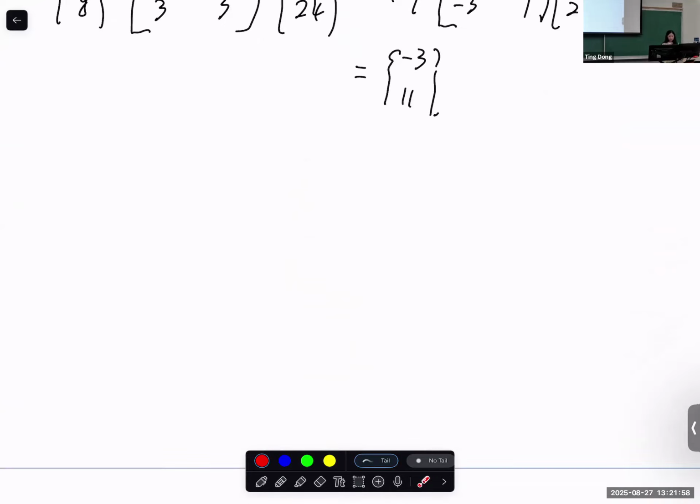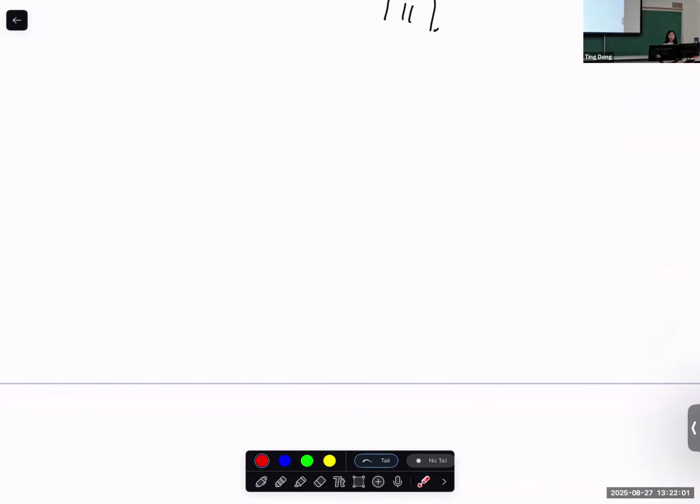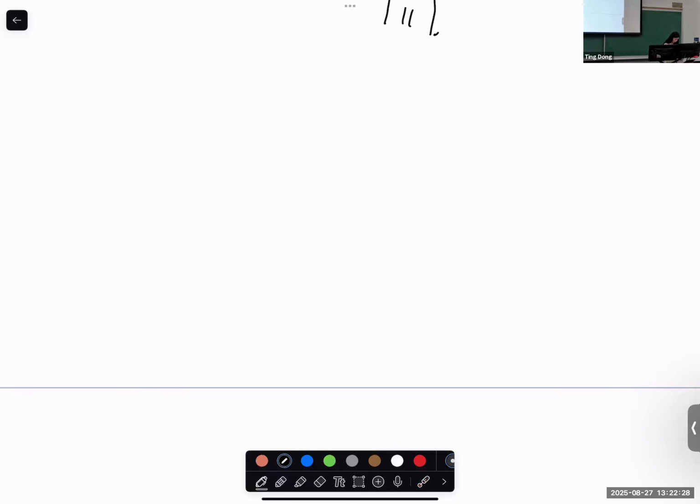We start with the simplest element type, which is a spring element. A spring element is simplest because it can only move in one direction, right? Let's say you have a spring, you cannot apply a force like this. You can only apply a force in the spring x direction. It can be either tensile or compressive. So for each node, there's only 1 degree of freedom, and the force can only be applied in the x direction. This is in the textbook, section 1.1, direct method for spring element.